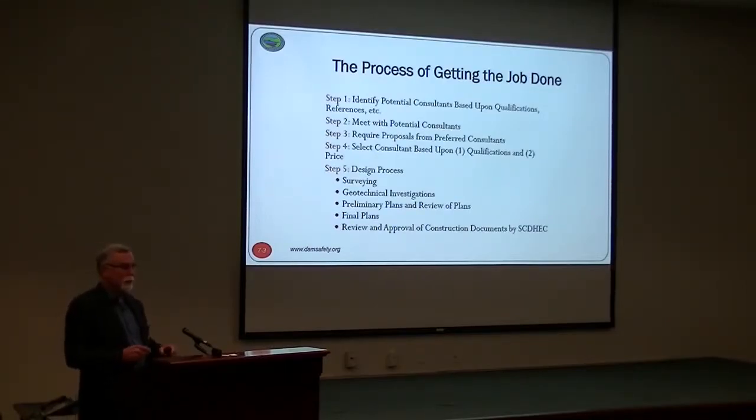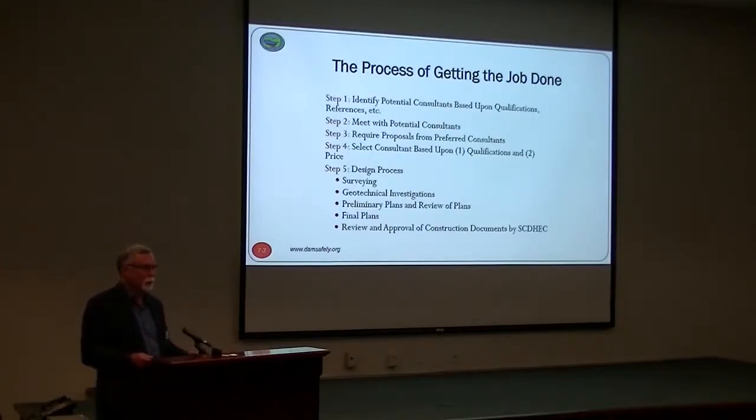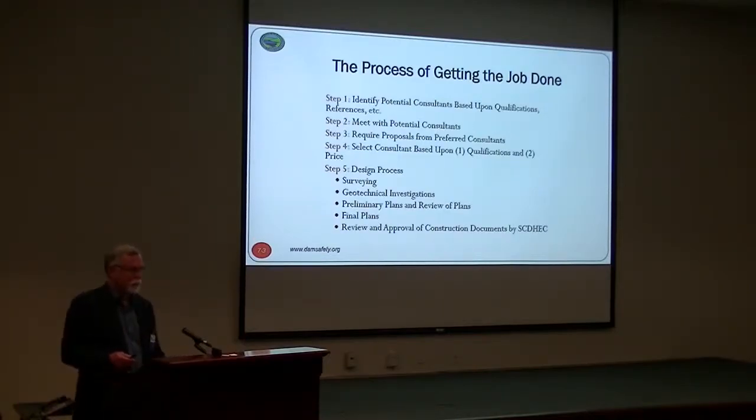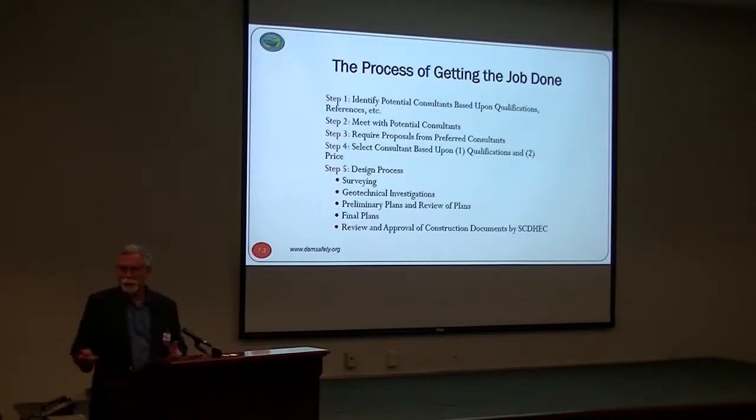A lot of times you have to have a surveyor survey exactly what's there right now: what the dimensions are, where everything's located, what the elevations are. You may have to have a geotechnical investigation, where somebody goes out and drills holes in the ground, takes samples of the soil, and sends those soils to the lab, and then you do a stability analysis and seepage analysis. At that point, preliminary plans and specifications will be developed, where the engineer will come back to you and say, here's what we found, here's what we think the solutions are. And at that point, you probably meet with the state also.